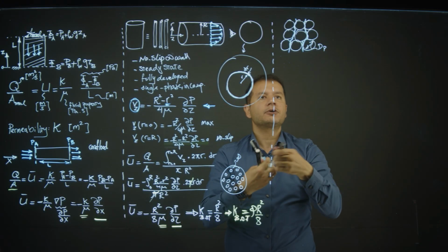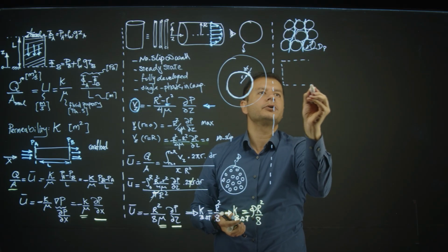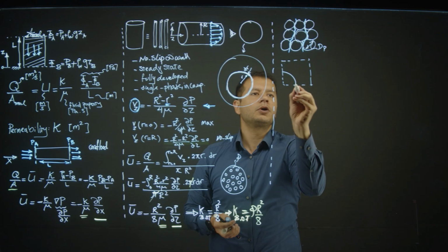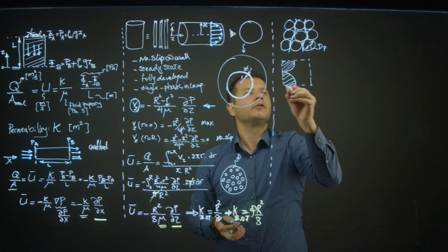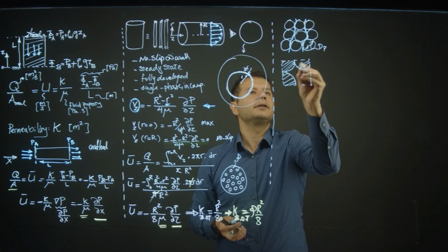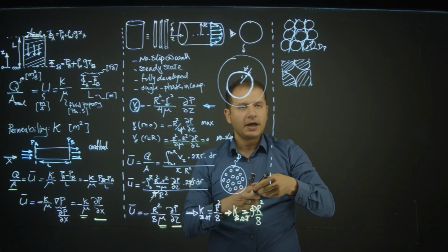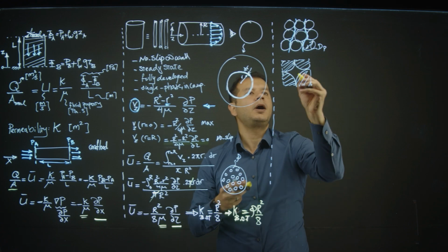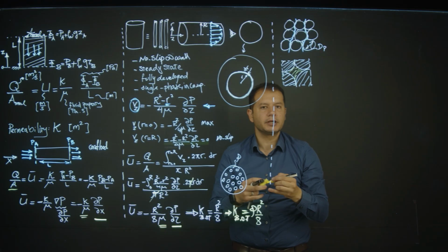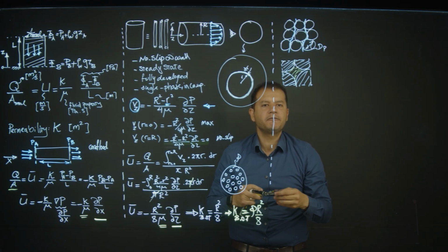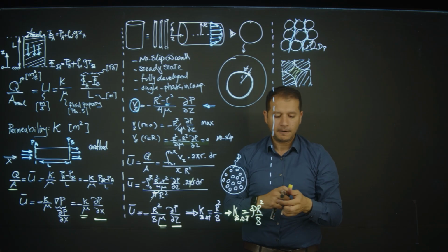They have a cross-section area like this unit cell that I'm going to plot for you. So this is a quarter of a grain. This is a quarter of the other. So like this kind of cross-section area. This is my grain, and the fluid flow happens in this yellow highlighted butterfly-shaped geometry. How can I find permeability for a butterfly-shaped geometry that is in here?